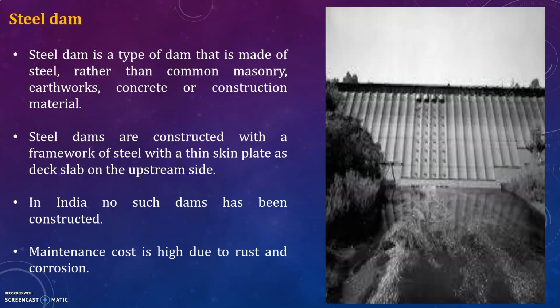Let us discuss some of the disadvantages. The first one is steel dams are lighter, hence are not as adaptable to absorb the shock from vibrations of spilling water. And also the life of a steel dam is known to be shorter than a concrete dam.